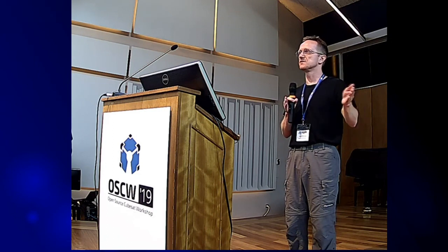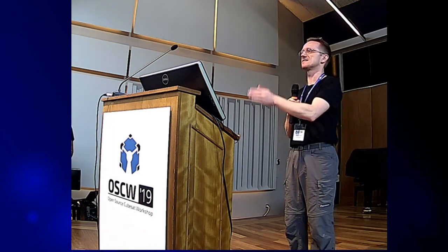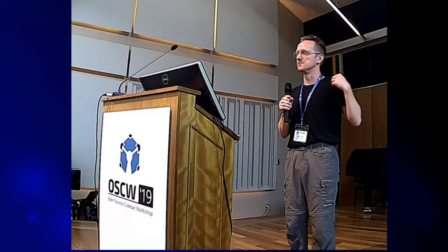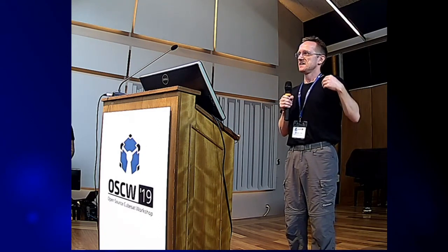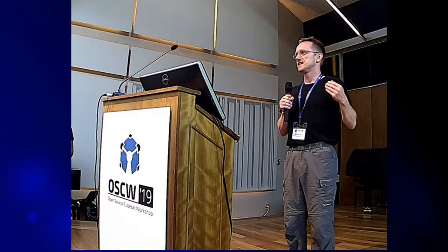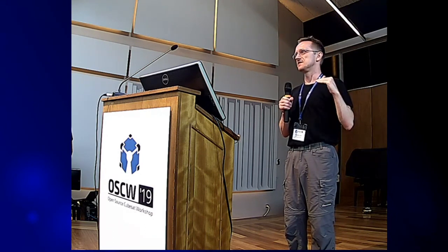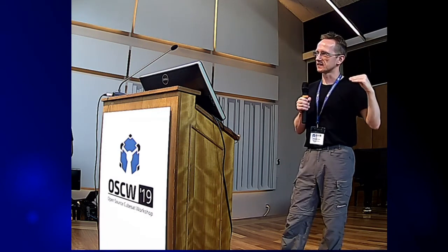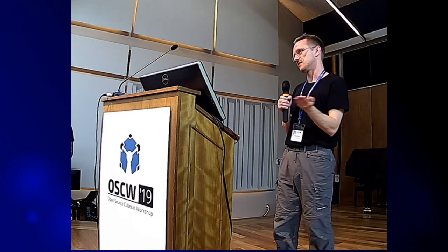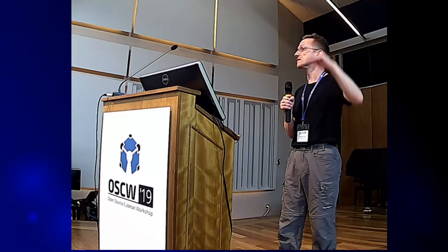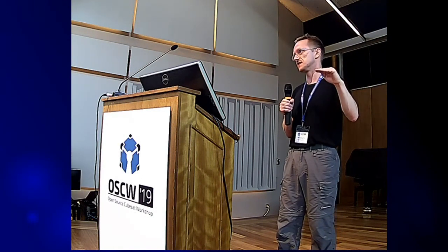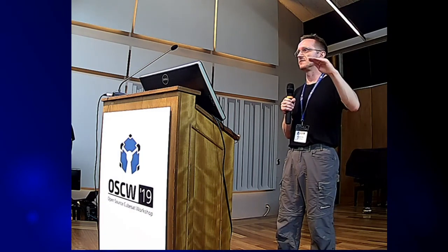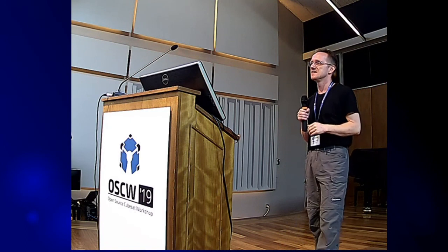So the versions of these APIs installed will be different. Therefore, I think it will be easier to have our own API and make sure we have an interface that's stable and fixed. So we interface directly to librtlsdr, for example, or libairspy. Those interfaces are stable because they don't change them anymore. They have the hardware, it's being sold, they just want to sell it. They don't update the interface.